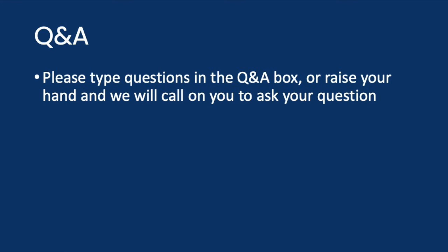Sure. Well, I'm assuming that if you're doing what I'll call unmodulated pulses, that is simple on and off pulses, not pulses that have some kind of chirp or phase changes in them, in that case, the best application would really be an analog signal generator. I know for Rohde Schwarz, all of our analog signal generators have an external pulse input, and there are various ways to control how the pulses are produced. We also have the ability, in terms of pulse input, to generate single, double, and arbitrary trains of pulses.